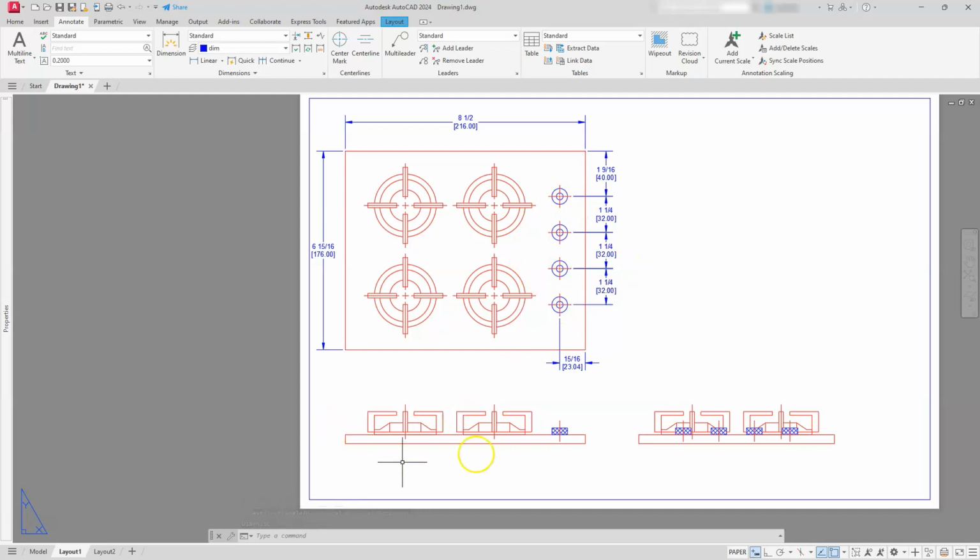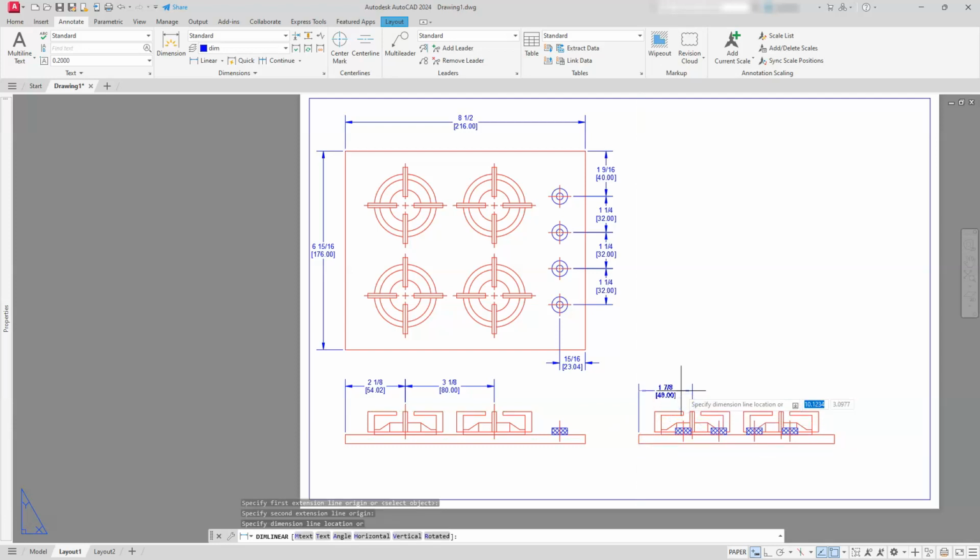As far as my eyes here, let's go ahead and put those dimensions here along the bottom. So let's go from that endpoint to here. I'm going to use the continue option, and then I'm going to place that one here. Likewise here, I'm going to do the exact same thing. I'm going to start off with a linear dimension. I'll place it from this endpoint to that center mark here.